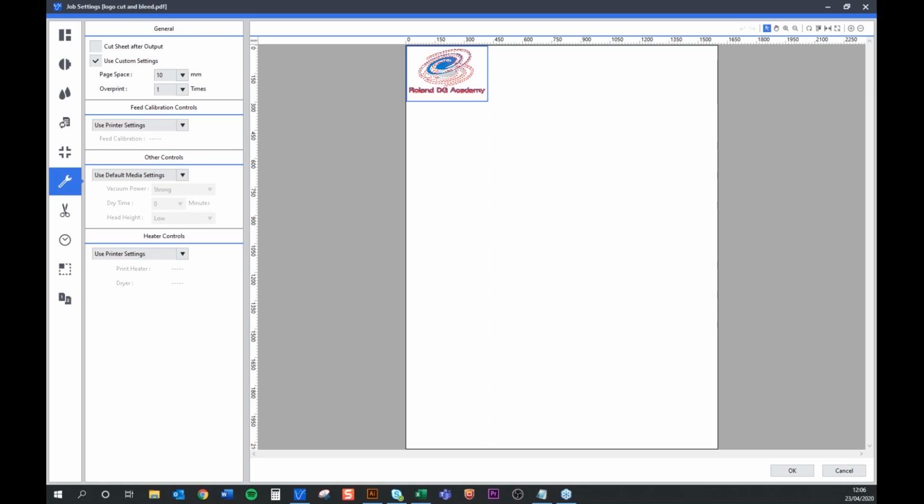But a couple of things you can check just off the top of my head. Make sure you've got enough ink in your machine that the machine can do its cleans. Make sure that the waste ink is emptied. Make sure there's no material left in your machine, so take it off the bed, don't leave it loaded. Do a test print before you go into your shutdown period so that you can check the condition of the nozzles and everything. You could cover your machine as well, with a light cover that you could drape over it to stop it collecting too much dust. But in essence, your machine can be left for periods of time without actually printing.